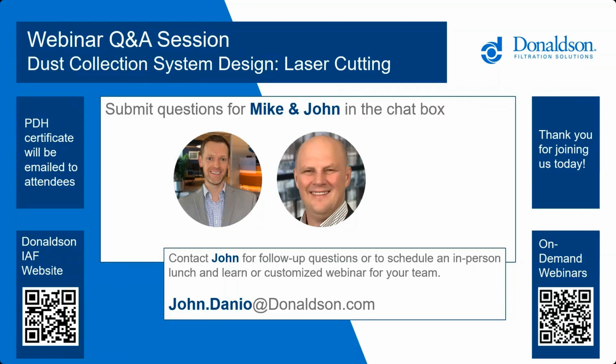That's the dust hazard analysis we mentioned previously. That's going to determine if the dust truly is fully oxidized, because to that person's point, that's kind of the key factor here. We can't always guarantee that the dust is going to be fully oxidized. And if the dust is not, that's a contributing factor to an event that could possibly occur.